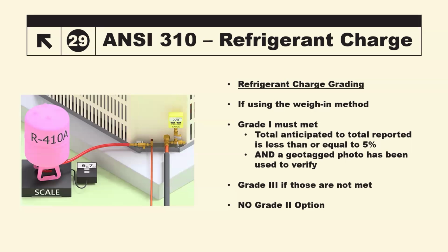As we see, if it's overcharged, you've got a problem of it not cooling. If it's undercharged, it overcools, with the possibility of freezing up the line set and/or coil in the system. And so that's what you need to avoid. That's inefficiency. If the coil is getting too cold too fast and freezing too fast, then you're reducing airflow into the system. You're also messing up its humidity control in the system. So you now have inefficiencies in the system. Again, that's why we're doing a report card and grading of the installation, to make sure that's done correctly.